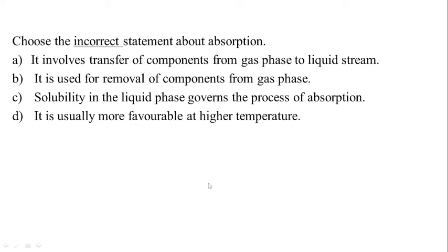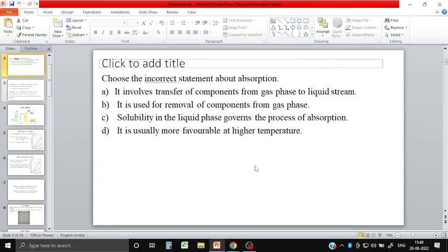Now what happens is, the pressure in this condenser will depend on what? It is supposed to be the bubble pressure of the liquid which is there. So if you have a lower temperature in your condenser, your bubble pressure will be less. And if your pressure in your condenser is less, your column top pressure is also less.